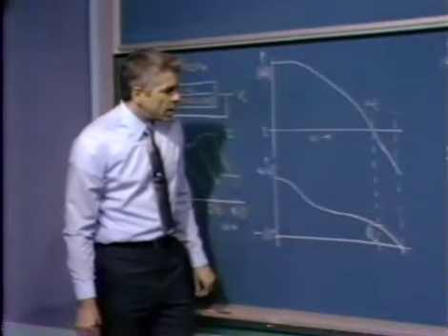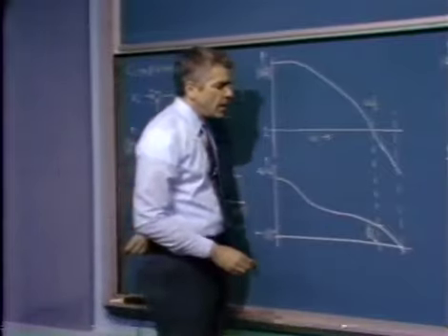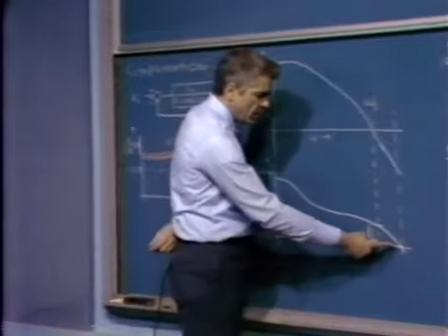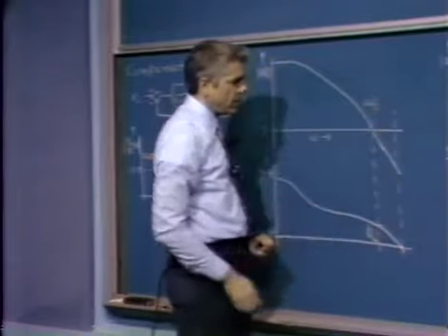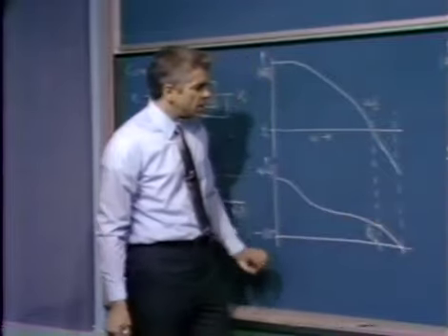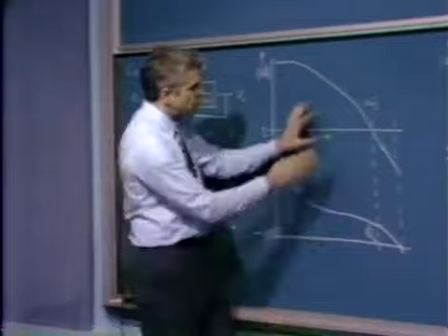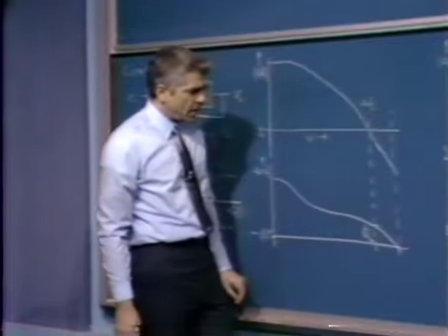The final quantity that we'd like to define is a quantity called the gain margin. And in particular, the gain margin is the amount of additional gain we could provide to the system, assuming we kept the angle fixed, before we incurred instability. So in this picture, it's the amount we could push up the AF curve before the system became unstable.